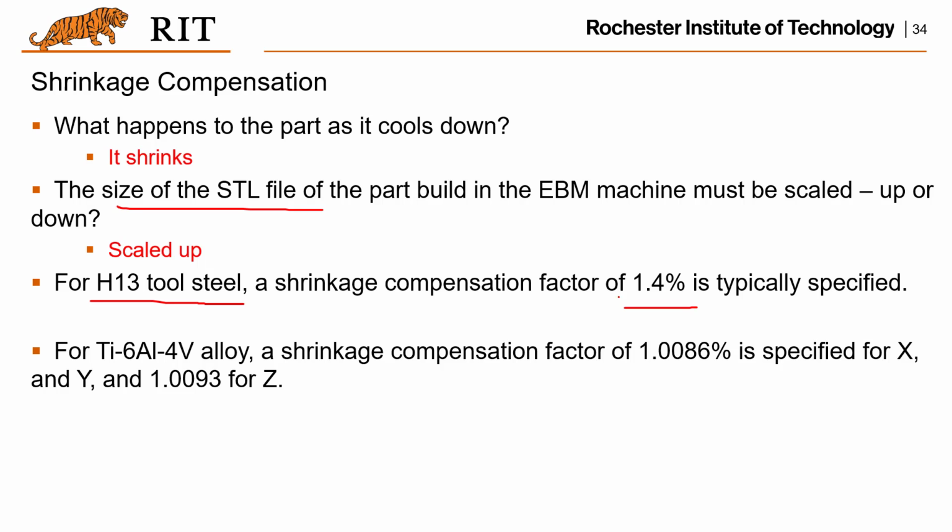Probably you need a scale-up factor of 1.4 percent. And for titanium alloy, probably you need to specify different scaling factors in different directions.